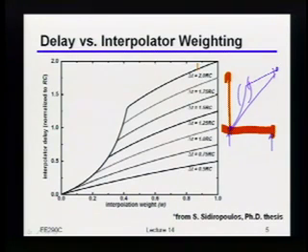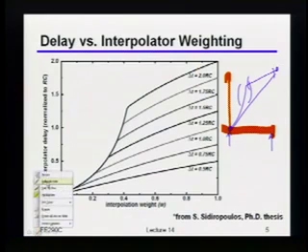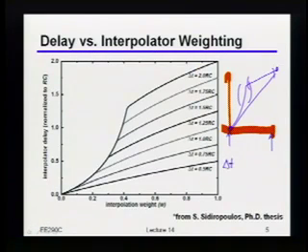When we say smooth, what we really mean is that the difference in the arrival times of those two clocks had better be basically equal to the RC of that stage at the output. And that RC is very much obviously related to the edge rate, okay? Does this make sense to people?